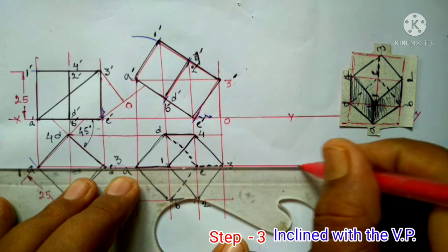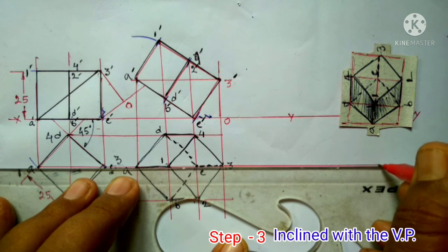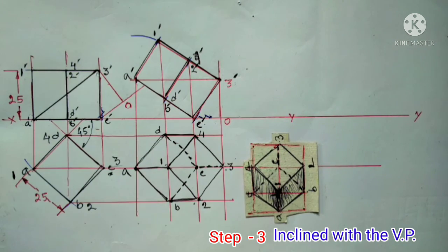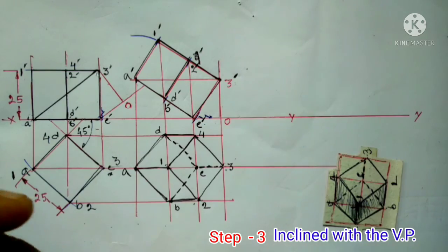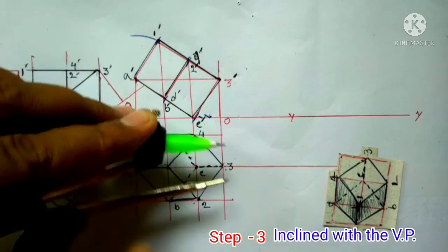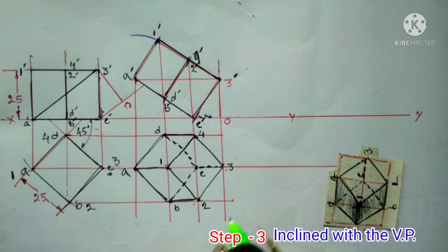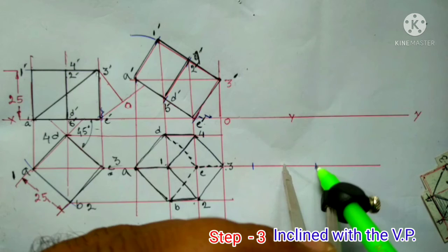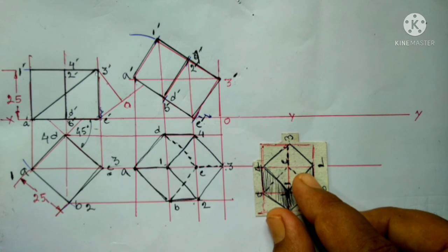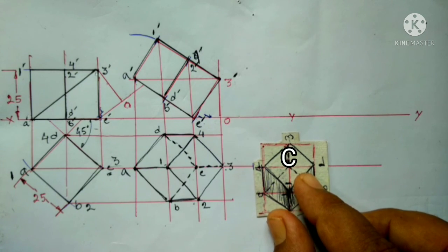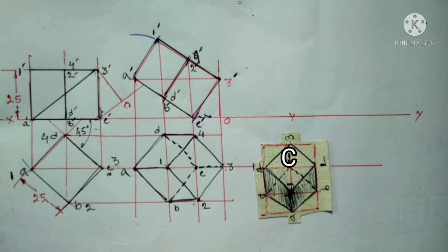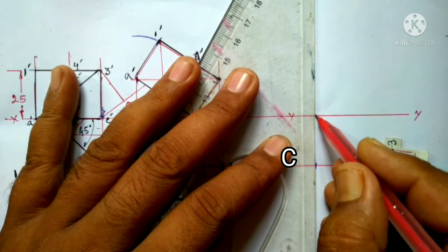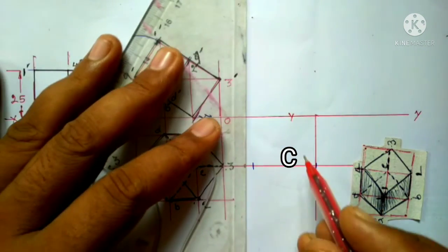First of all, draw a projection line from the point C' which is parallel along with the XY line. To draw the rectangle made by projection line, consider point C as a midpoint. Compare with this figure, mark the midpoint C as the cube is resting on this point. Then draw the perpendicular projection line on both sides of point C.